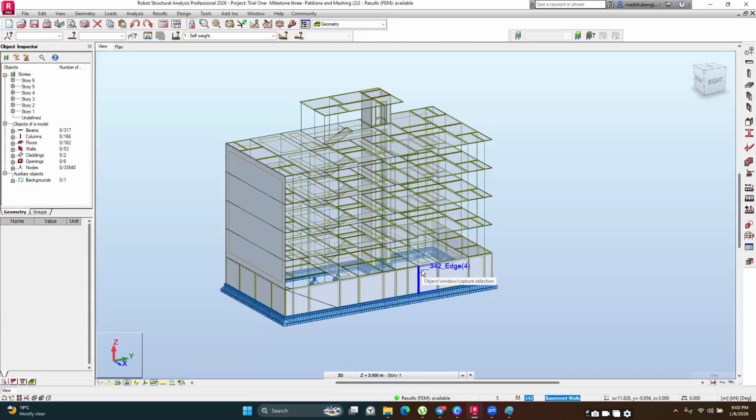But if they are not viable, they are going to fail in the design phase. Once they fail, you have to take the precautionary steps, so if it's increasing the cross-section sizes of the members or increasing the depth of the slabs, then you do that. Okay, so let's visualize the results.